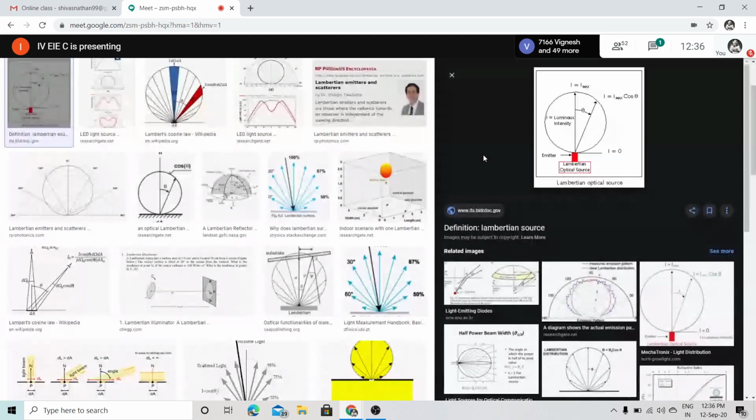If I create a change in my optic fiber cable with respect to an electric field, that will give me a path to measure voltage. And similarly, if I have a change of plane of polarization with respect to my magnetic field, that will help me a lot in measuring current. Okay, and these are all accurate measurements. So we are speaking about fiber optic sensors. Okay, so everything will be more accurate.